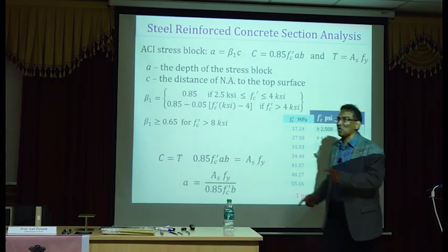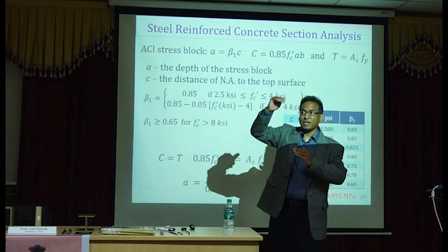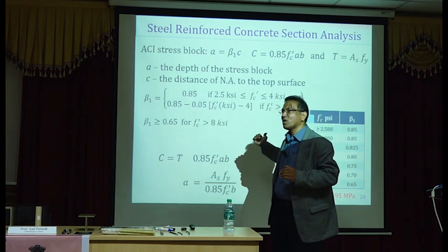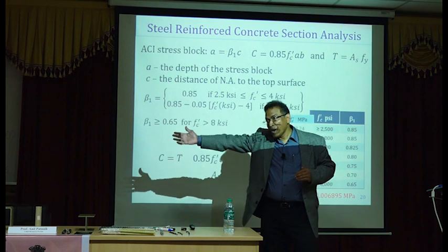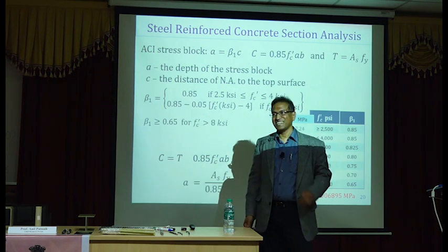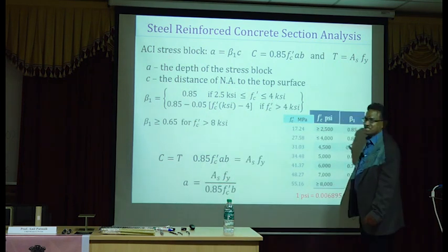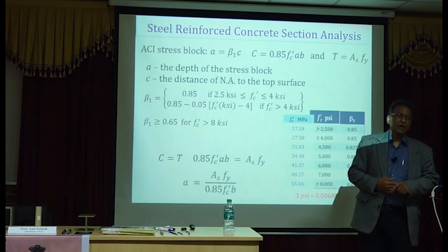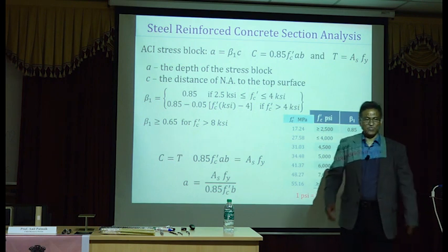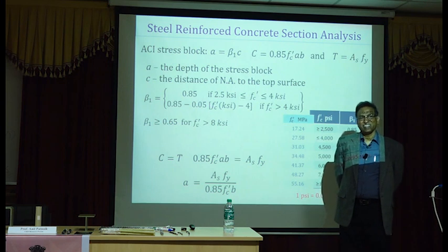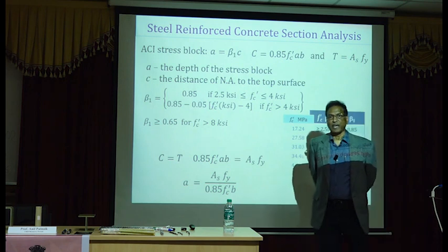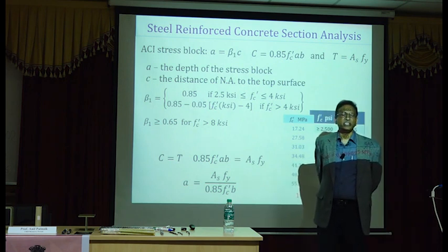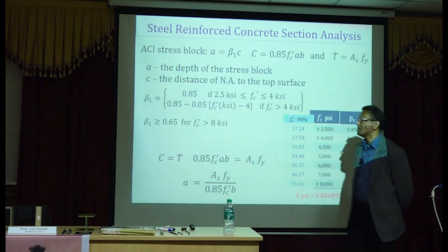So you are right, that's a good point. So there is another layer there. But that's not in here because in design we don't want to consider that. That is the supplier end of the equation. Good point. That aspect is there in IS 456, yes, but we are not following it. Statistical mean is there in IS. I'm sure it is there. As you say, we are not following it. The compliance is very, very low. But I'm sure in some major projects they do that.